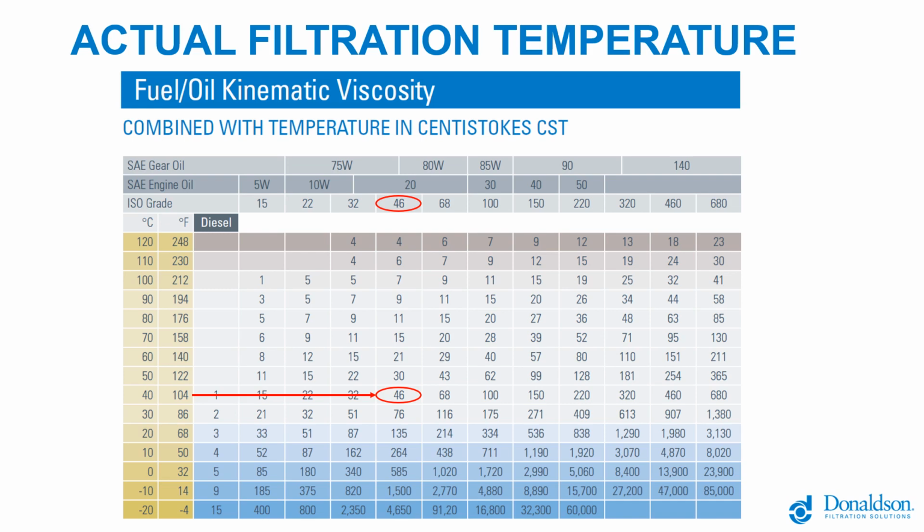That's nice thin hydraulic fluid. It pumps very easily at that viscosity, and it's even thinner when it's actually in service and working. However, at room temperature, that same fluid has a viscosity significantly higher than that. It has a viscosity of 135 centistokes. So it's now gotten about 4 times more difficult to pump or push through a filter.